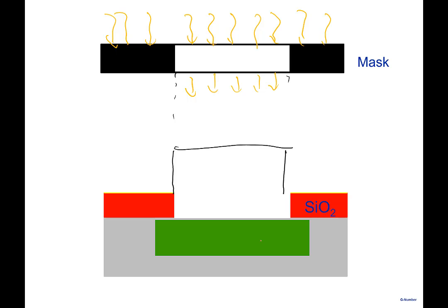Now, all these steps that you're seeing here, putting silicon dioxide, putting a photoresist, exposing it, these are what we call different process steps. So a foundry, wherever these things are manufactured, an engineer there or their team would know how to do an SiO2 deposition, how to do photoresist deposition, how to expose it, and things like that. They're process engineers, they know how to do all of that.